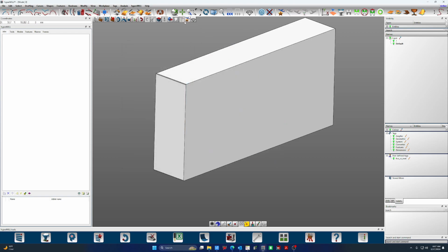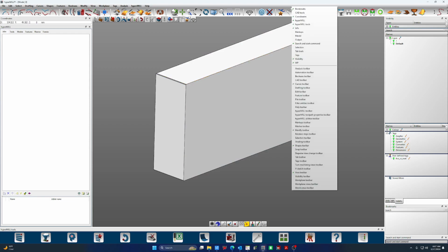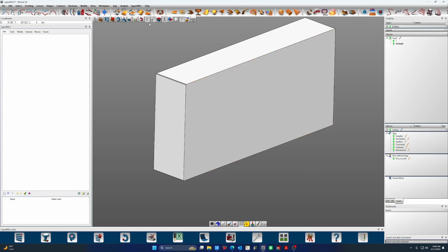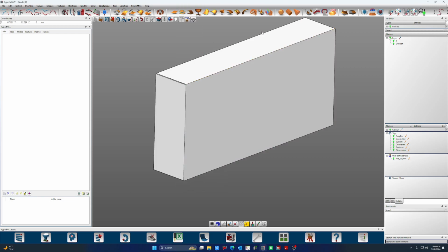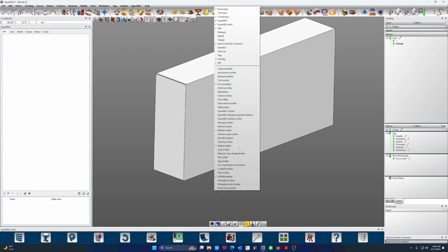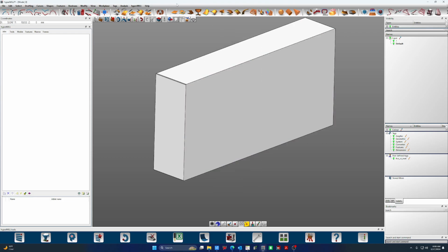These two buttons here are buttons that I've added that didn't actually default when I redefaulted my screen, so I could show you guys what the default looks like. But we'll discuss adding those because they are both super useful. The rest of those I don't find so much. Visibility toolbar. This has some color stuff, hide, unhide. H, Control H. You're going to live on those two keys. Hide, H key, unhide, Control H key.